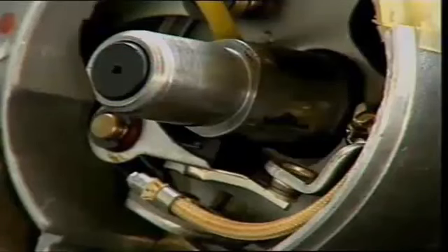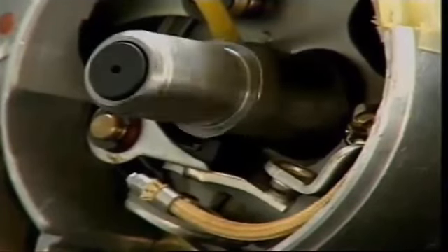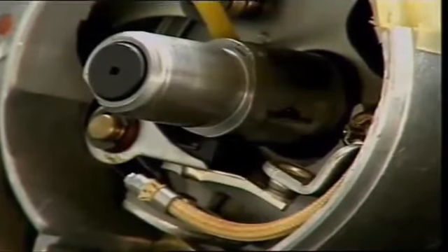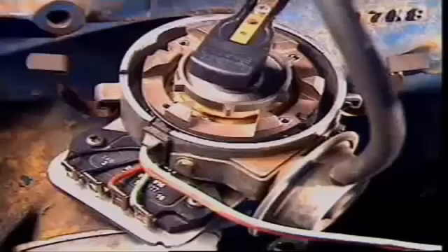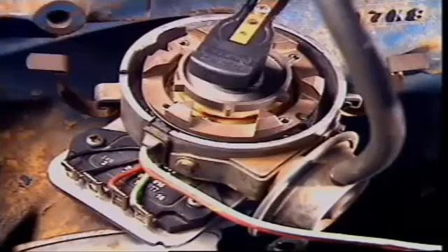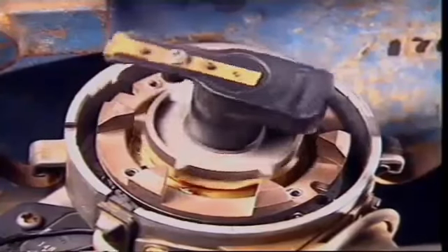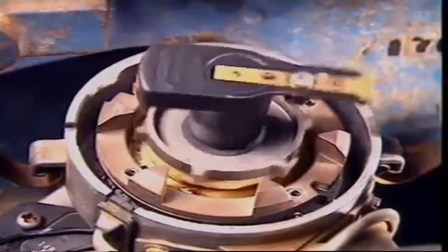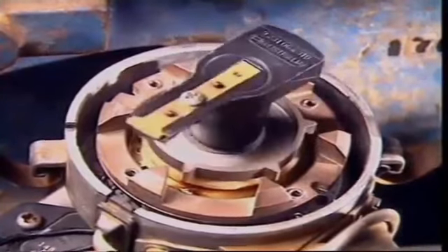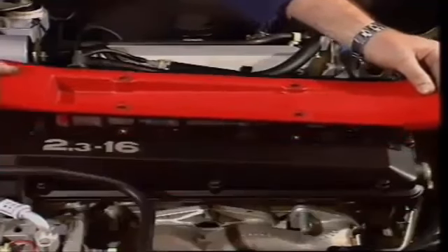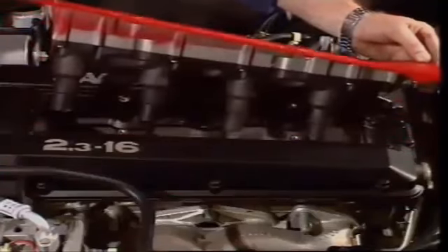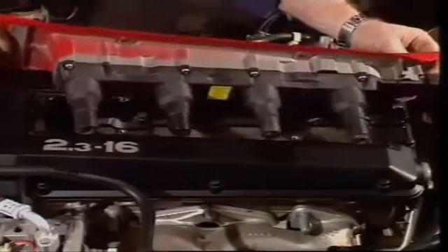There are three general types of ignition systems: Breaker ignition uses contact breaker points in the distributor to initiate the spark. Electronic ignition doesn't need contact points. When a signal is received, triggering occurs through transistors in an ignition module. Direct ignition has no distributor and uses coils to supply high voltage direct to the spark plugs.